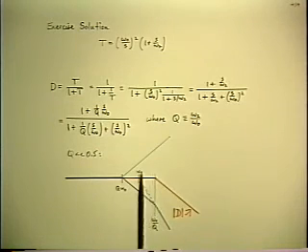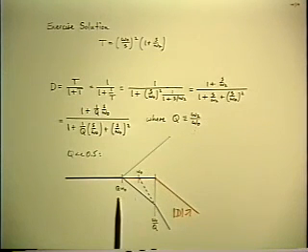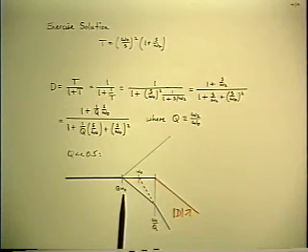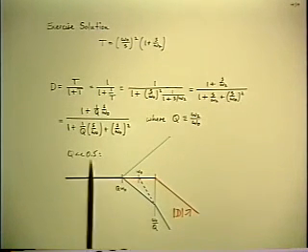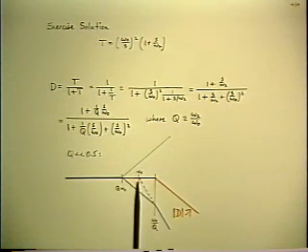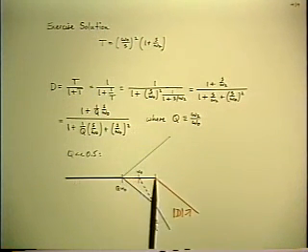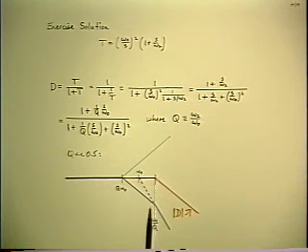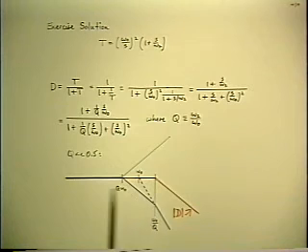And you see that in this limiting case of real roots, one of the roots of the denominator cancels the 0 in the numerator. So the result, which is D, the closed loop discrepancy factor, simply remains flat until you get to the second pole of the denominator, because that's all that's left. And then the closed loop gain will drop off at the single slope.